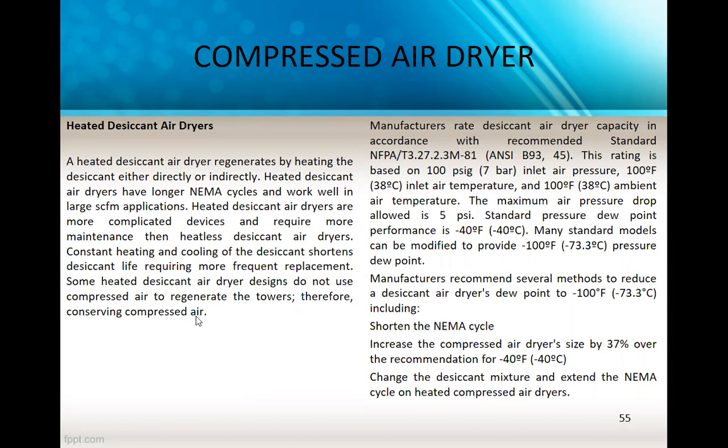Heated desiccant air dryers are more complicated devices and require more maintenance than heatless desiccant air dryers. Constant heating and cooling of desiccant shortens desiccant life, requiring more frequent replacement. Some heated desiccant air dryer designs do not use compressed air to regenerate the tower, therefore conserving compressed air.